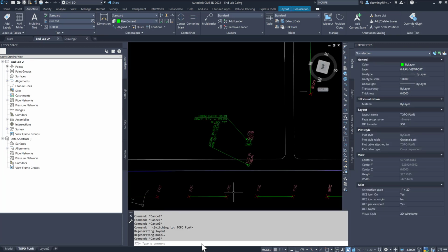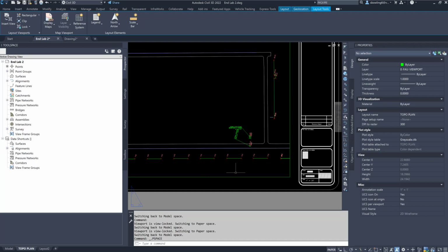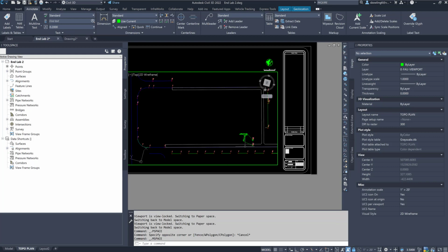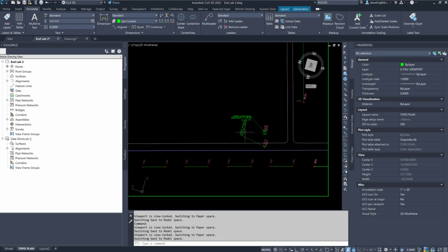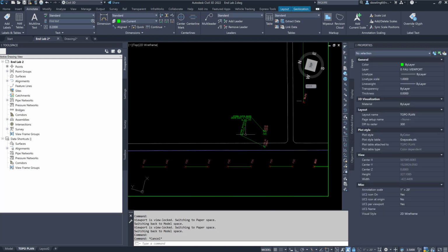Okay. Now, look how this looks versus this. Okay. So there's also another command. When I'm not active in the model viewport, it'll be this color here. If I double click on the out, see how it goes a little bit darker or more green or whatever color you use. It's bolder. Okay, here's another command. MA for match properties.